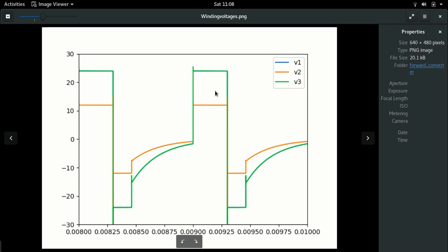It's important to note that even though winding 3 is 24 volts, it's completely useless because of the polarity of the voltage and the polarity of the diode. The diode will not allow this to conduct. Only when the switch is turned off does this reverse. And this reversal happens because of winding 3. Now winding 3 drives voltage in winding 1 as well, negative, and also at the same time through winding 2. Of course, this is the stage where this is freewheeling, so there is energy supplied back to the input. Once this diode stops conducting, that is when this voltage begins to decay to zero.